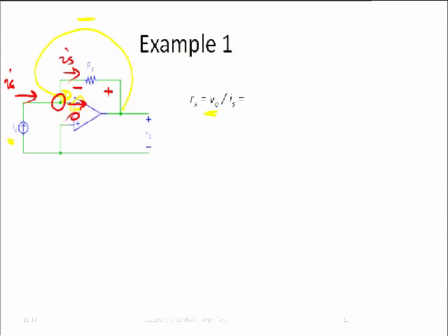Well, what is this voltage here? 0 volts, right? Therefore, let's make this a ground. So this is 0 volts. Then what's the voltage at the node where it's 0 volts, right? Consequently, this voltage here is V out minus 0. That just happens to be V out also, the voltage across the resistor. And then we again have this funny Ohm's law with minus signs, so Rx is actually equal to Rf.